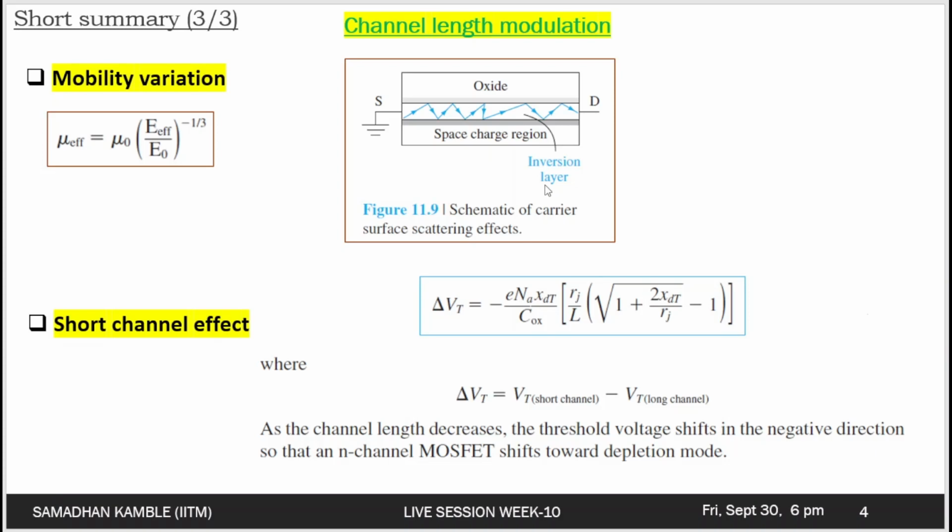The inversion layer charge is induced by a vertical electric field, and a positive gate voltage produces a force on the electrons in the inversion layer towards the surface. And as the electrons travel through the channel towards the drain, they are attracted to the surface, but then they are also repelled by the localized Coulombic forces.